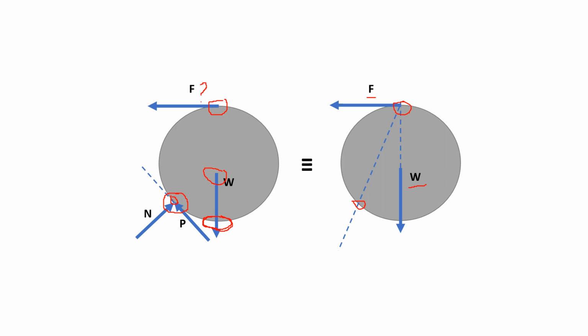So with the definition of the three-force member, since F and W are not parallel to each other, the third force must be concurrent with the line of action of F and W. It means that the line connecting the point of application of the force here in this portion and the intersection of the lines of action of F and W would be the line of action of your third force.